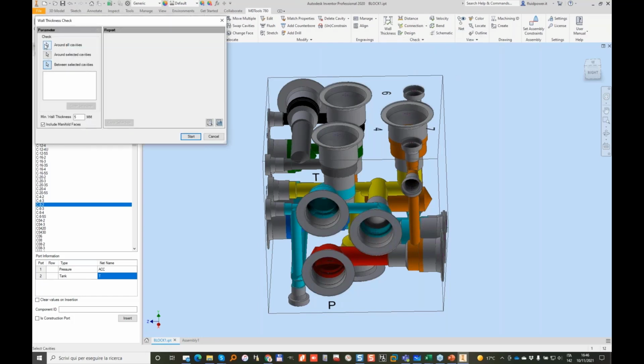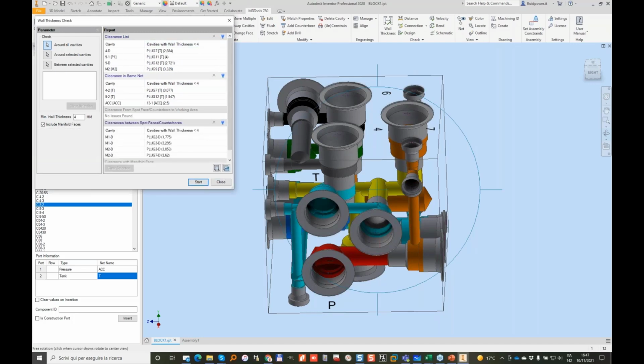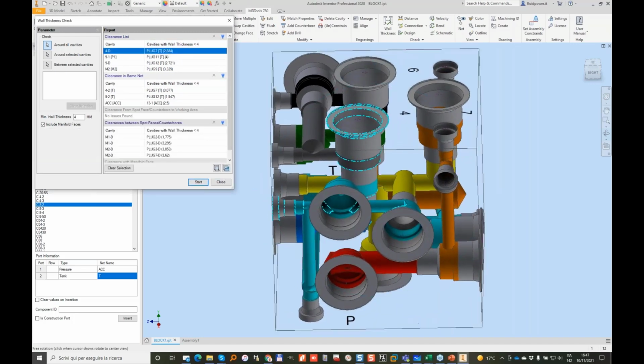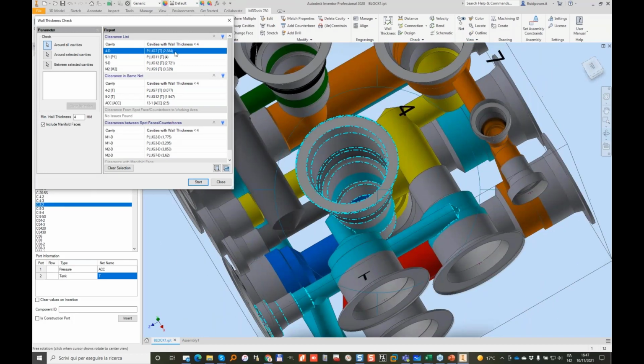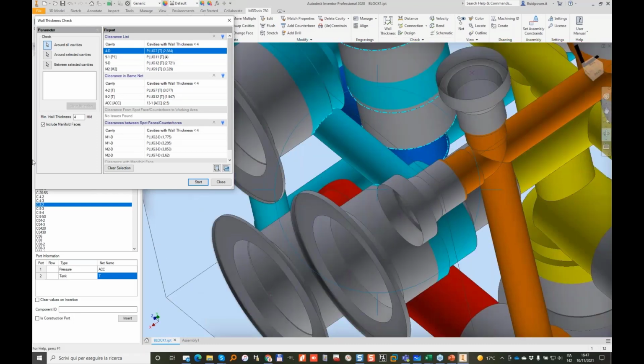Wall thickness is important as well, but even if you have places where the wall thickness is not enough according to your standard, still the block may not break. So it's really more important to verify the connection. So here you see that we have some places where the wall thickness is only 2.8 millimeters. So it's here actually. With a bit of eyes, you can view it. I show you something, a different way for viewing wall thickness. That's the last information for today.